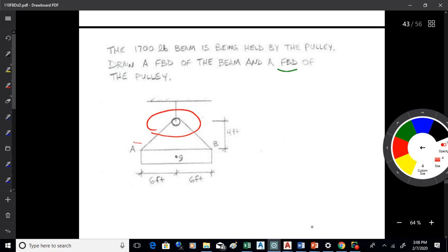If I want a free body diagram of the beam, I'll draw a boundary around it like that. That's often how I start. It's funny, obviously you can just look and see those things, but just drawing that boundary helps to point them out. You don't tend to skip over them carelessly, because now you start seeing, oh yeah, I cut through this or that.